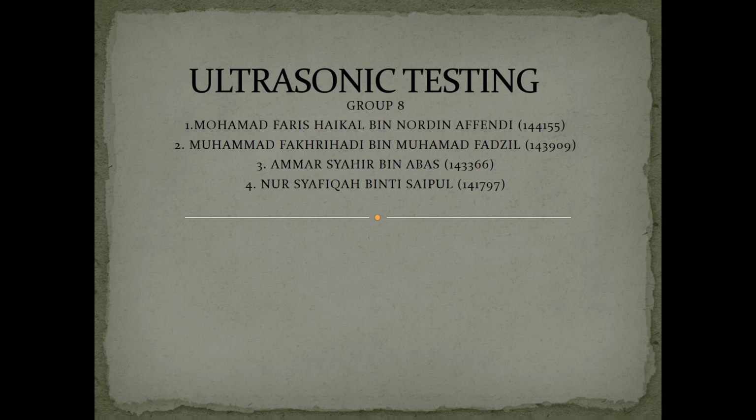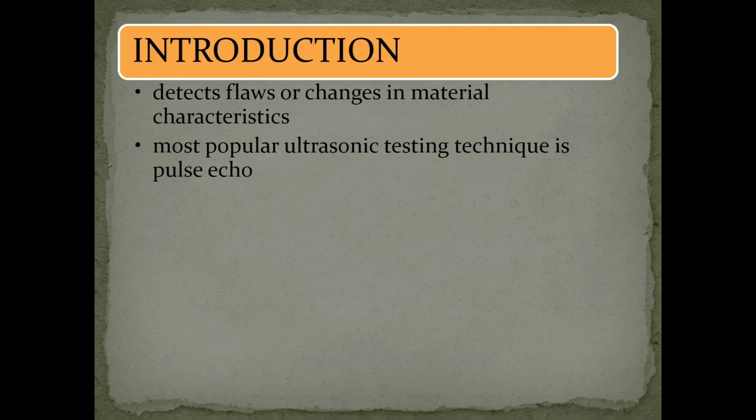Today I would like to present my ultrasonic testing. Ultrasonics detect flaws or changes in material characteristics by transmitting high frequency sound waves into the material. The most popular ultrasonic testing technique is pulse echo, in which sound is injected into a test object and reflections from internal flaws or the part's geometrical surface are returned to a receiver.